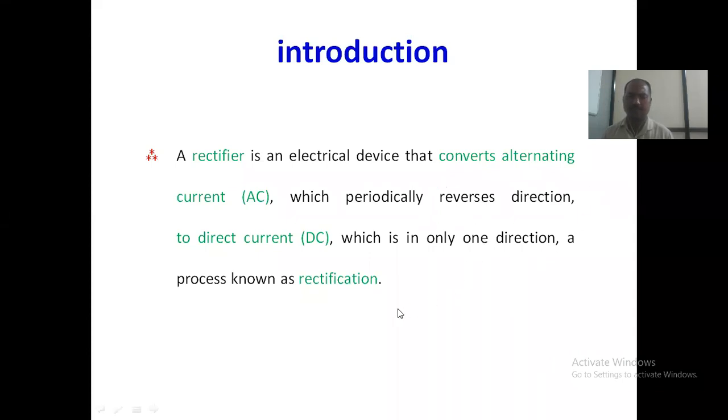These are the things with respect to rectification. Rectification indicates a device which converts AC voltage into DC voltage. DC indicates direct current, which should not change with respect to time. But in the case of pulsating DC, this is not the case; there are some changes. So for removing those changes, we have to use a regulator as well as a filter circuit. These are the introduction of the rectifier.